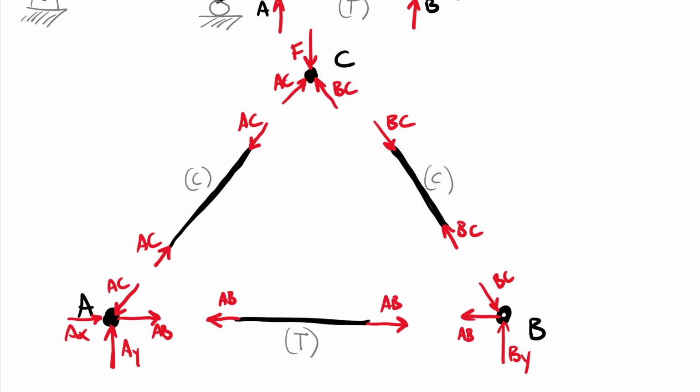You've been introduced to external forces. We only have one external force in this problem. It's going to be this force up here, F. You've also been introduced to reaction forces, right? So the reaction forces in this problem are AY, BY, and AX. So once again, this is an external, or you can also call these applied. And then we have our reaction forces.